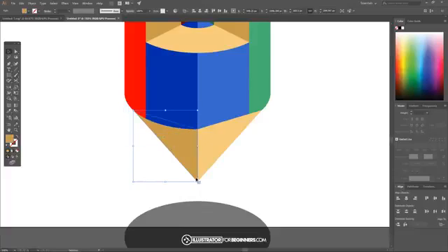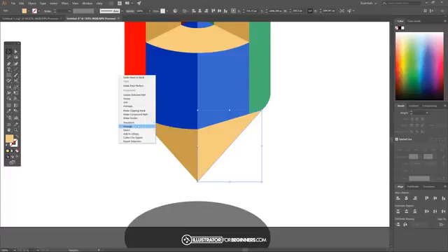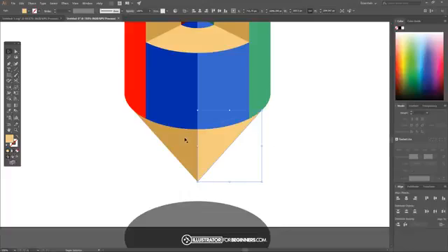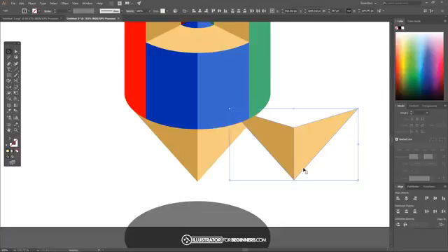So it's beneath everything down there. And then we're going to do the same thing. Right-click, click on that object, right-click it, Arrange, Send to back. And what I want to do is hold Shift and click on the other shape so we have them both selected, and hold Alt and click and drag to create duplicate copies. And then hold Control and grab the bottom node and snap it back onto the bottom node over here.